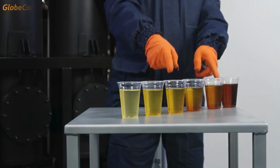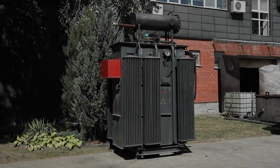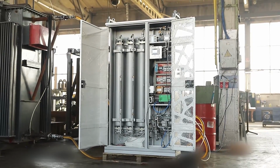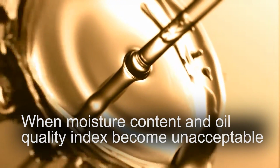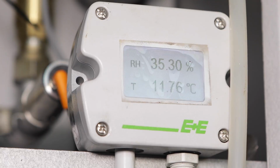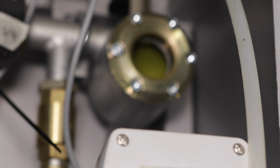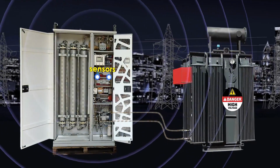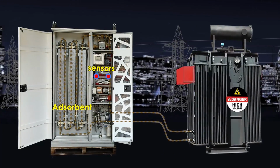But if its parameters deteriorate, you still need to tend to the transformer. This task is also addressed by the TOR system when the moisture content and quality index of the oil deterioration reaches a certain level. Filtration and drying are automatically engaged and last until the amount of moisture in the oil is back to normal, after which these functions disengage automatically.